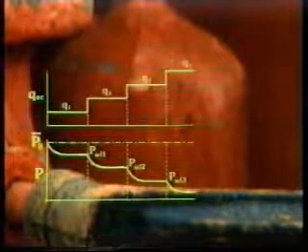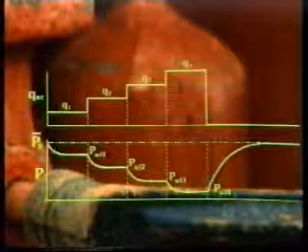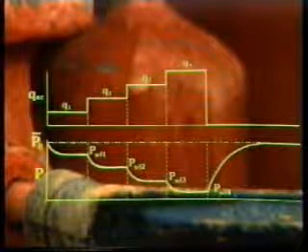The well is then flowed at the next higher rate, and the flowing pressure at stabilization for that rate measured. The test is continued until the 4 rates have been measured and the appropriate log-log plot made. Generally, the flowing pressures are measured at the surface. This requires that the measured values of the stabilized pressure at the surface be converted to sand face pressure using appropriate correlations. More about those correlations later.